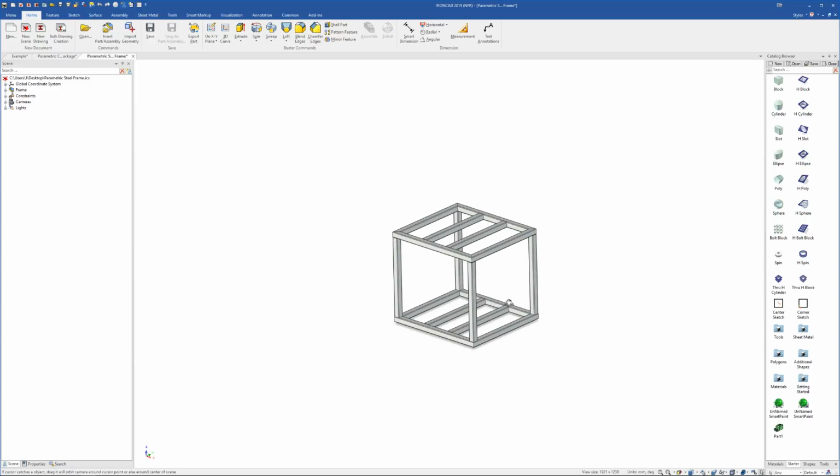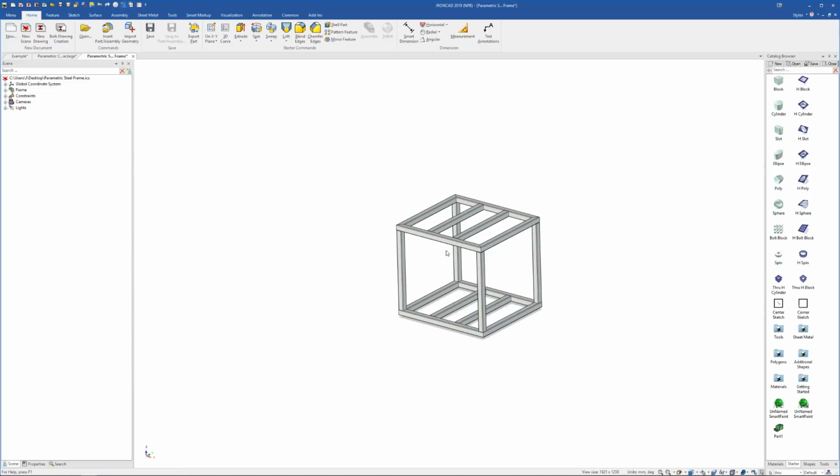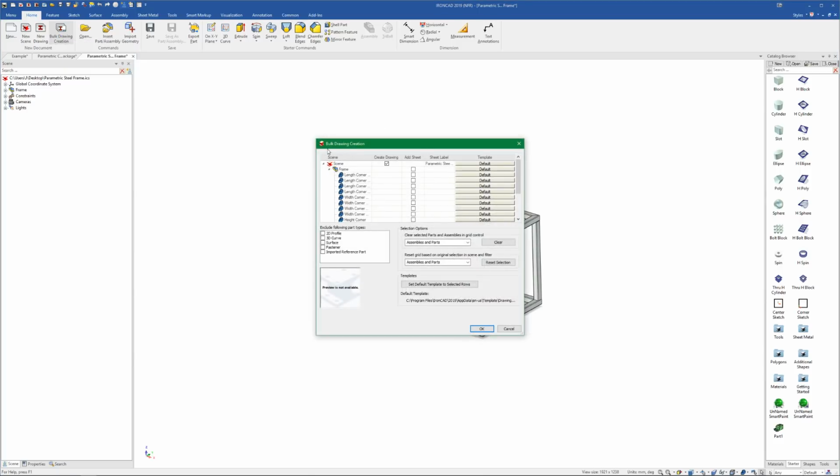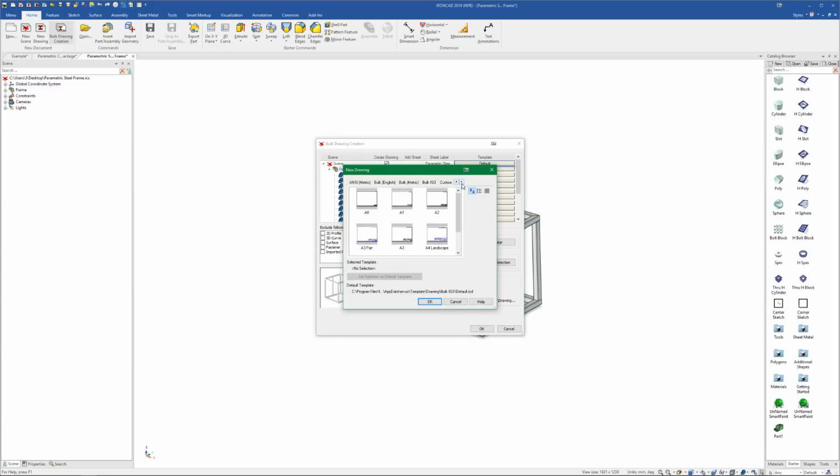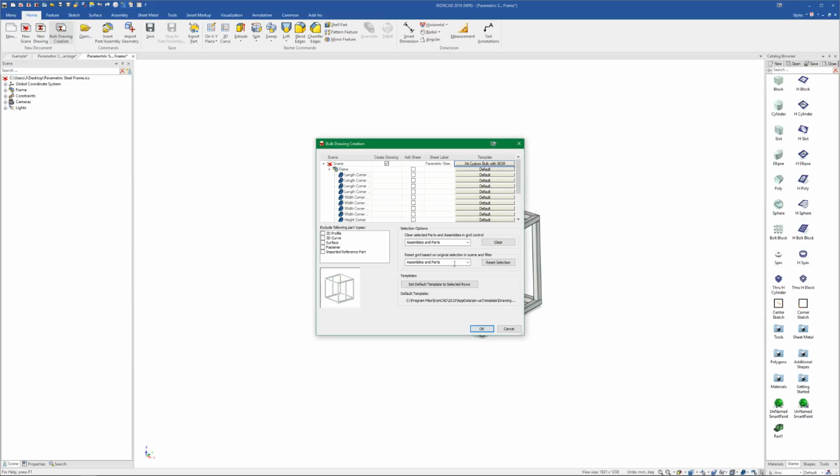One thing that is often very overlooked is the bulk drawing tool. I'll quickly show this before we do the BOM export thing we're talking about. It's really worth getting used to using this because it's extremely powerful. You can just click bulk drawing, and I won't go through it in detail here because it's not the main thing we're focused on. Basically, I'll select my bulk drawing and do this one with a BOM. It's just an A4 sheet, a pretty simple one.